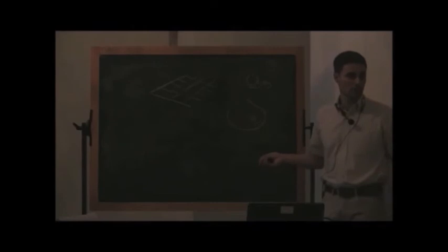So let's say that I consider Q scalar n, the vertical force. This is my plane, I take a normal in the plane of the plate, and Q scalar n is the vertical force along this line. This is the definition of the shear force. So let's assume that you have this normal.